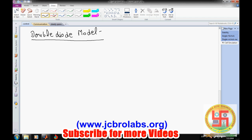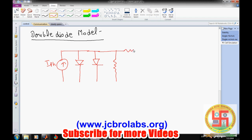So if we draw it again, there will be some IPH current, that is the photodiode current, and then there is one diode here, and another diode in parallel with it, and similarly there is a shunt resistance and the series resistance. This is the total voltage which we are getting out, and this is the I, this is RS, this is RSH, this is diode 1, this is diode 2. The current flowing through them is ID1, ID2, and the current through the shunt is ISH.